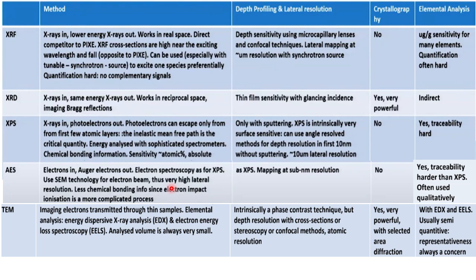With Auger electron spectroscopy, crystallography is not possible, but elemental analysis is. If you compare XRF and AES, obviously higher atomic weight elements give much more prominent results in XRF, whereas Auger electron study is usually done for low atomic weight elements.